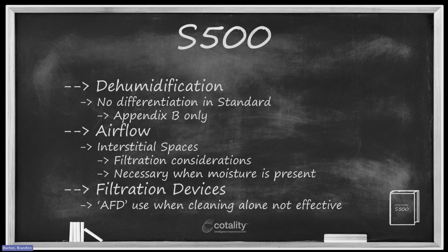In airflow, there's a little bit of information about specialty drying systems. When you take a look at air movement and managing airflow in the project, there is conversation in the S500 about starting at the most basic and getting a bit deeper, conversation about ensuring that you do get air movement across all wet evaporating surfaces, right?